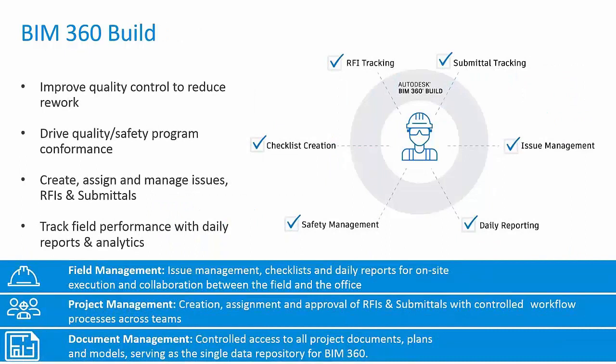So, breaking down BIM 360 Build into a lot more of what you can do, as I mentioned: RFIs, submittals, issue management, but you can also pull daily reports as well. So you can see which contractor or where the most issues are assigned to on a particular job or project, helping you analyze where there might be a pinch point on a project for any particular reason. You can then analyze that information and see why so many issues are occurring with a single contractor, or why so many issues are occurring on a certain location of the site or the project as well.